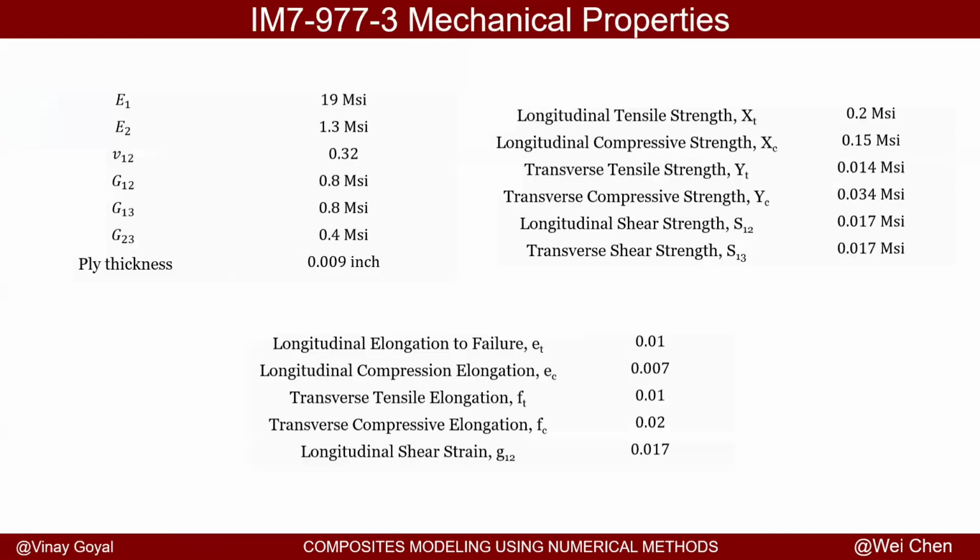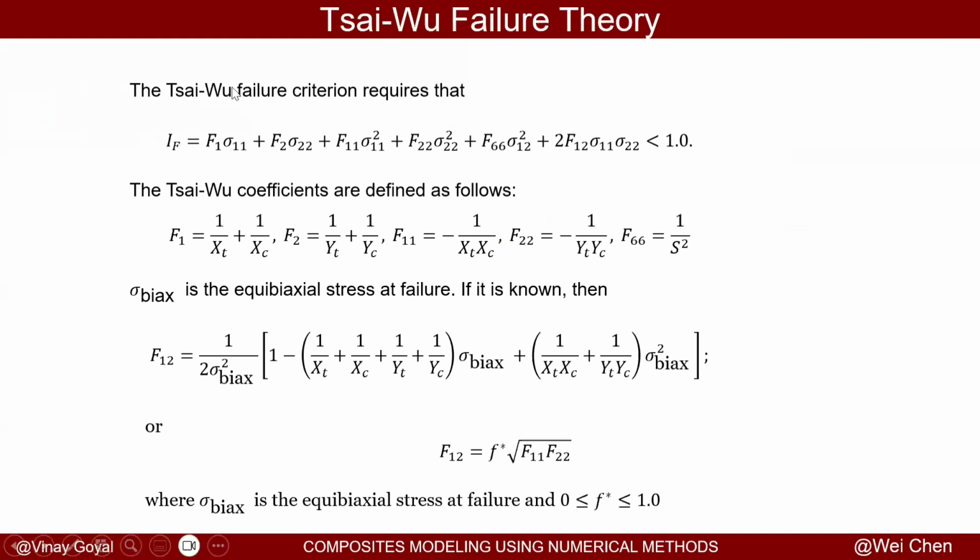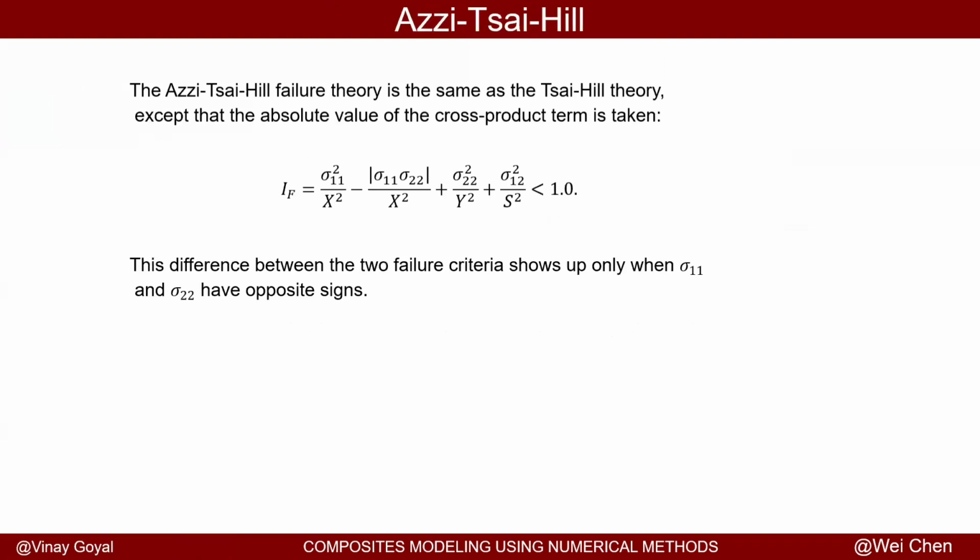And when I say failure indices, what I'm talking about here is Tsai-Wu, for example, has this criteria. If it achieves 1, then the very first ply could fail. And that's called first ply theory. We're not saying the whole laminate fails, but in this assumption, we are. As is Tsai-Hill, the failure index for that, if it achieves 1, then that's when failure occurs as well. Now, again, that's an assumption.